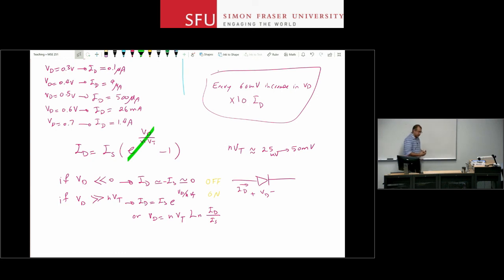It depends on your application. If what you can measure is 1 milliamp at minimum, maybe 10 microamp is your zero. And if you can measure down to the picoamp range, maybe femtoamp is your zero. But on means that you're letting a considerable amount of current go through your diode. Off means that you are not measuring any current through the diode. It may be there, but it's just so small that it's of little value or importance to you.